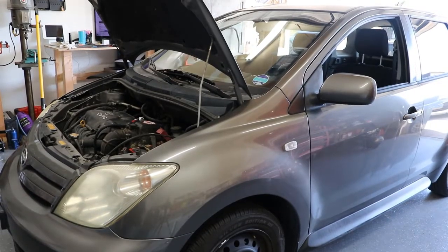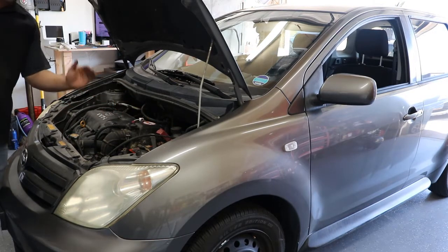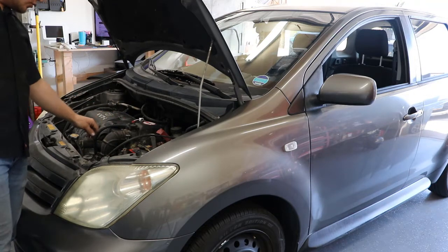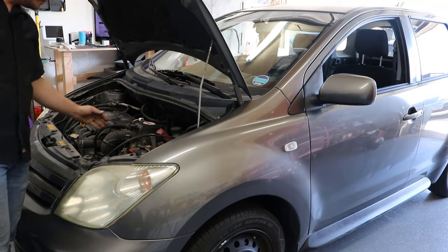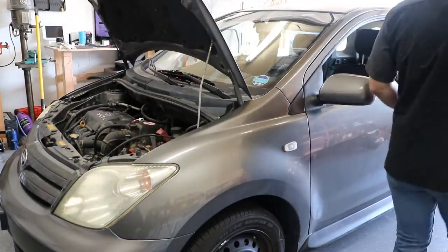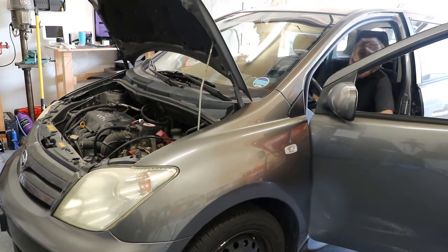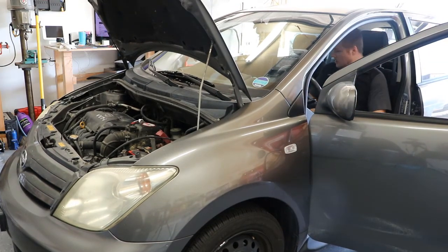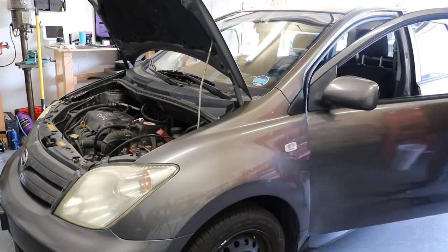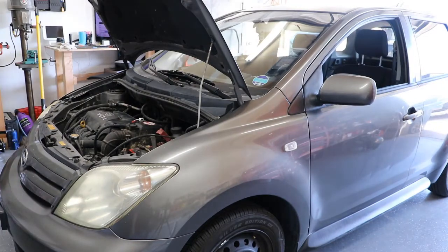Alright guys, so here we are again. We have the car up and running, we have the valve on. I tested the valve, it is activating with the scan tool. We have our brand new hose here for the vacuum, which is great. I am going to take it out for a drive. So that's basically it. This should be fixing the problem. I tested the rest of the system. As you saw, there were no other leaks, so we're looking good so far. No check engine light, but I'm going to take it for a little bit of a drive and see what we get.